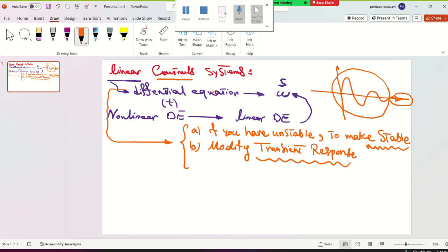So we're going to modify it with respect to what? With respect to, say, MP, remember? Maximum peak overshoot of the system. We want to modify it to keep it at 25%, based on the demand of your boss, or settling time, we're going to define it. And C, your controller has to be able to remove the steady state error signal that we're going to show as e(t).